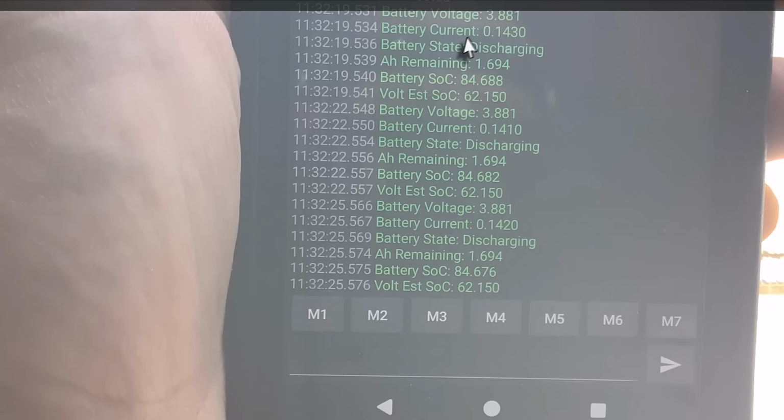So now we can see the battery current is no longer negative. It's 140 milliamps. And that's what it takes to power the circuit and the ESP32 and the RGB LED and things like that. So we can see the battery is now discharging, right? And if we go down here, I guess the voltage for the battery is pretty steady. Notice the voltage dropped pretty quick. That's because now the battery's under load. When the battery's not under load, its voltage jumps right back up. And of course, the voltage will slowly drop as it discharges. But the idea is we're just running off of battery power.